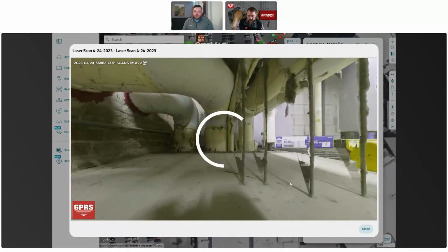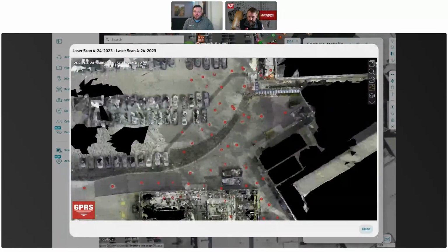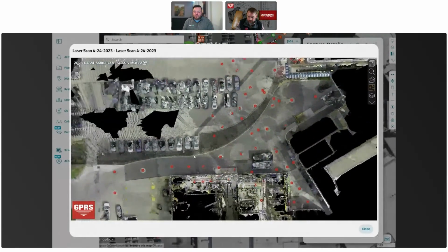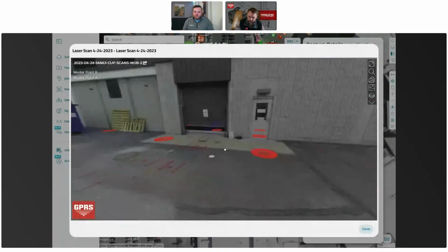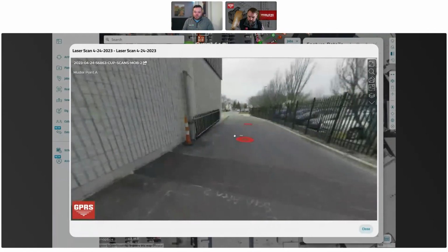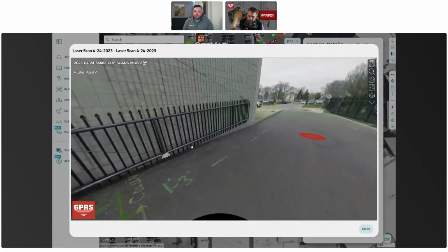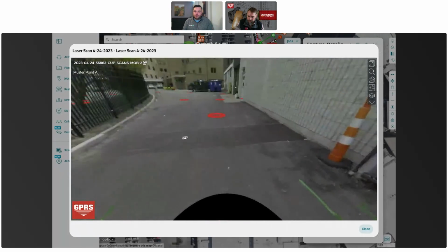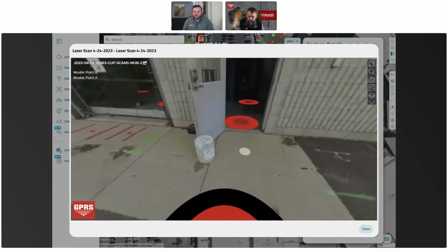So this was a project that we worked on with a local contractor here. They had been tasked with expanding a central utility plant just adjacent to an existing utility plant. And you can imagine all the utilities that would be in the way of a project like that. This particular site was a riverbed at one point, so we actually had to put caissons in to support the structure. And just imagine putting those caissons around all these different electrical duct banks and storm lines and the like.